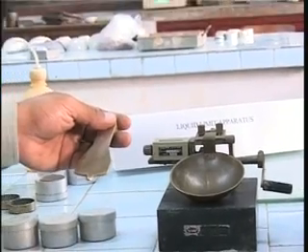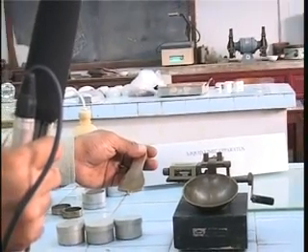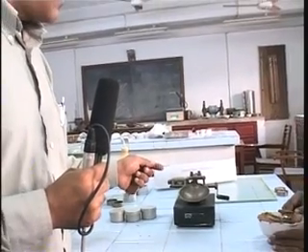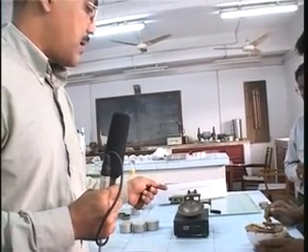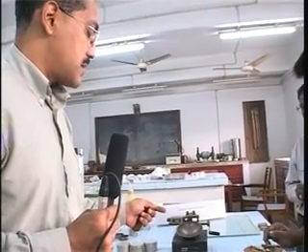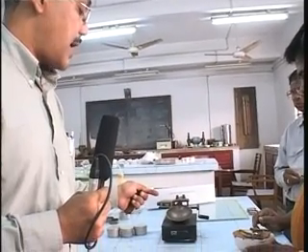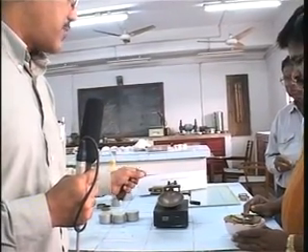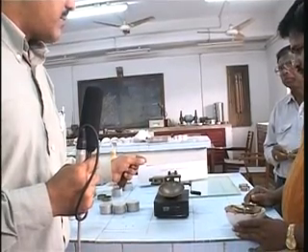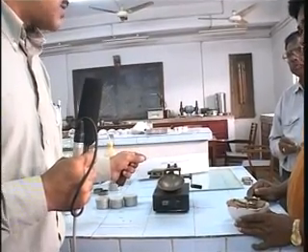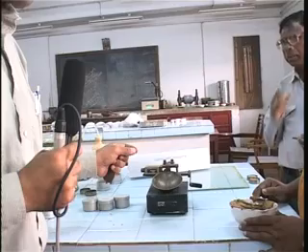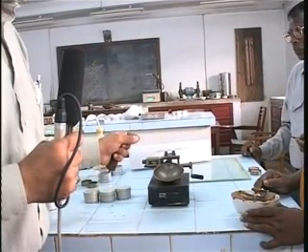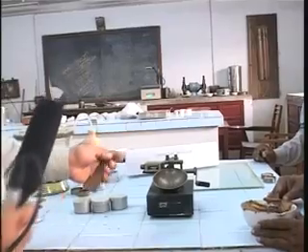You can imagine that as the soil becomes drier, you are going to require more and more blows for closing the groove, and we are going to plot it up in a semi-logarithmic scale, and we are going to find out what is the moisture content required for 25 blows closing the groove by 12.5 millimeter. You are going to see that in the next little bit.